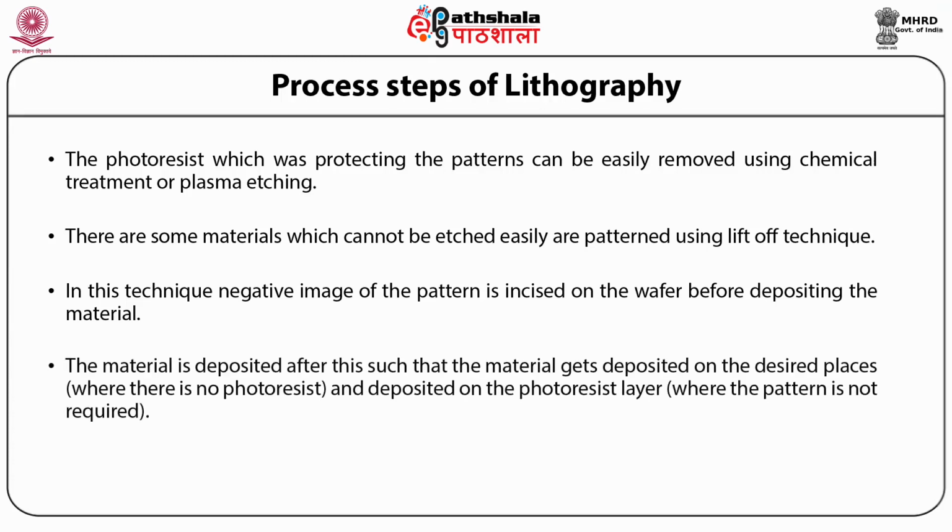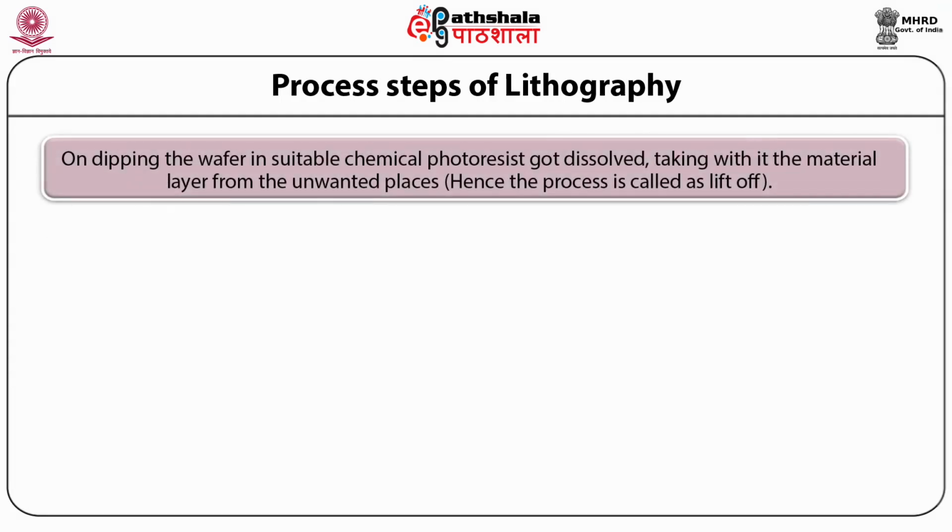The material is then deposited such that it lands on the desired places where there is no photoresist, and also on the photoresist layer where the pattern is not required. On dipping the wafer in a suitable chemical, the photoresist gets dissolved, taking with it the material layer from the unwanted places. Hence this process is called liftoff.